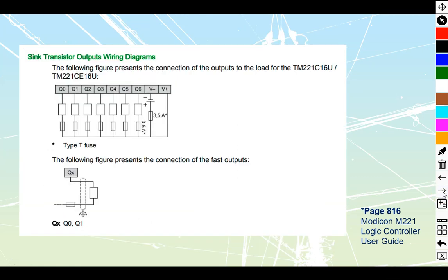And the very last type that we have is one other type. It's a lesser used one. It's got the U designation over here. And it is going to be a sync type. And you'll note that the negative of this power supply is now the one attached to my common terminal. The common terminal in this one being the V negative. And I'll explain that one once again in a later video.